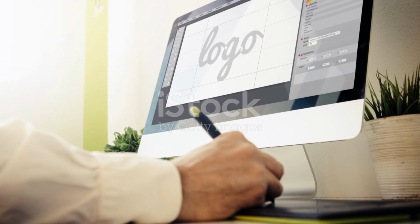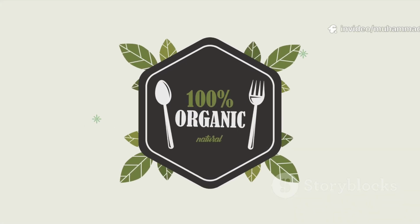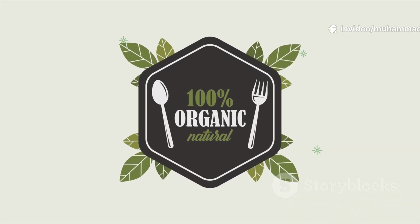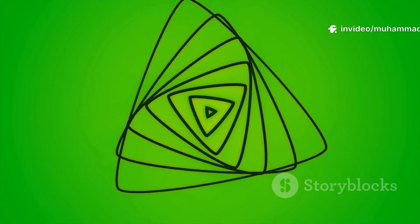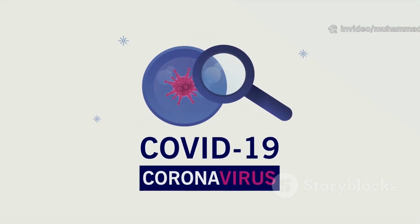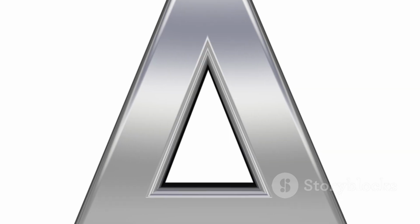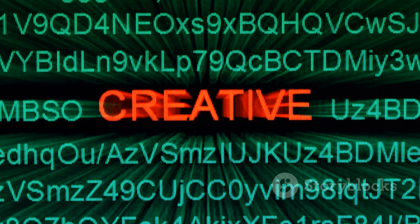Let's make the logo look authentic with the exact Chrome colors. We'll use hex codes for precision. Select the top ring section, open the Fill Color Picker, and enter #EA4335 for red. Select the bottom right section, enter #FBBC05 for yellow. Select the left section, enter #34A853 for green. For the center circle, enter #4285F4 for blue. Each section now matches the real Chrome logo. Using hex codes ensures perfect color accuracy.